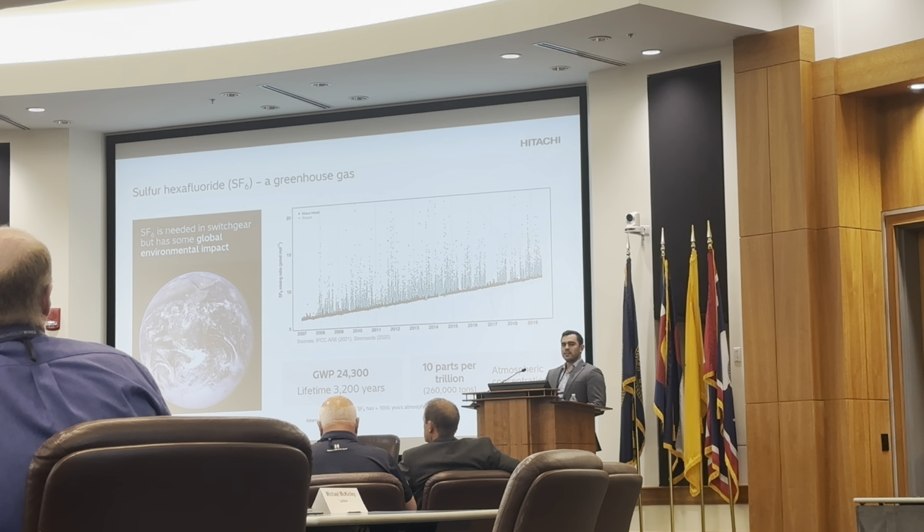I think your question's like, what's the max current rating? Is that what you're asking? Yeah. Oh, the current rating would be, on the 69 kV, you're looking up to 4,000 amps. On the 170 kV, up to 4,000 amps. On the 230 kV, you're looking at a short circuit of up to 80 kA, but you're also looking at current of up to 4,000 to 5,000 amps.